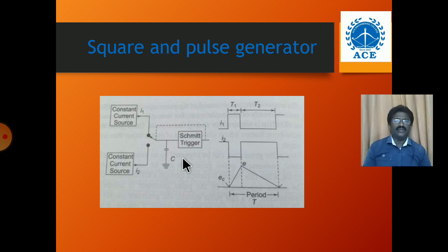The ramp capacitor size is chosen by the multiplier switch. The multiplier switch and frequency control provide decade switching, and the frequency range of this generator is covered in 17 decade steps from 1 Hz to 10 megahertz.